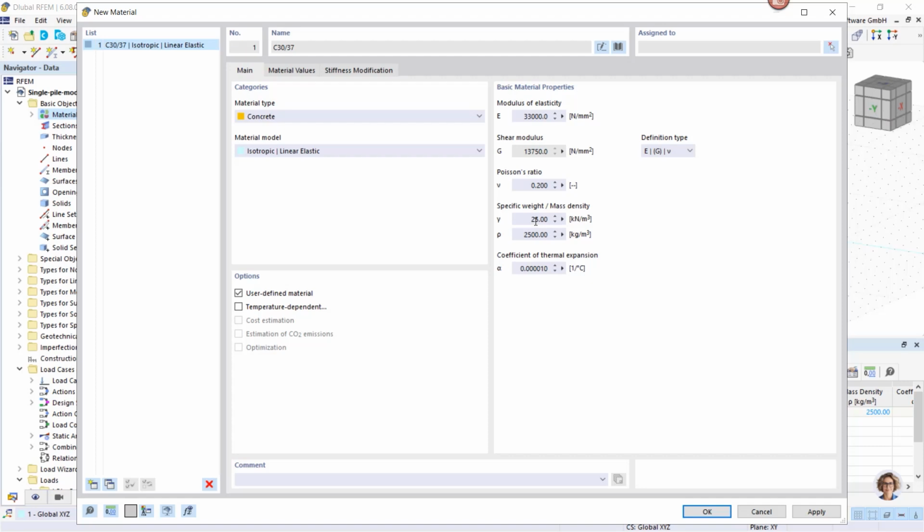The specific weight is reduced in this example as it is a 1D object, and in the area where the cross section of that pile would actually be placed, there is a soil material placed. And this soil material already has weight, so as they overlap, the cross-section of the pile and the soil self-weight, we put here a smaller weight so that the sum is the right value.